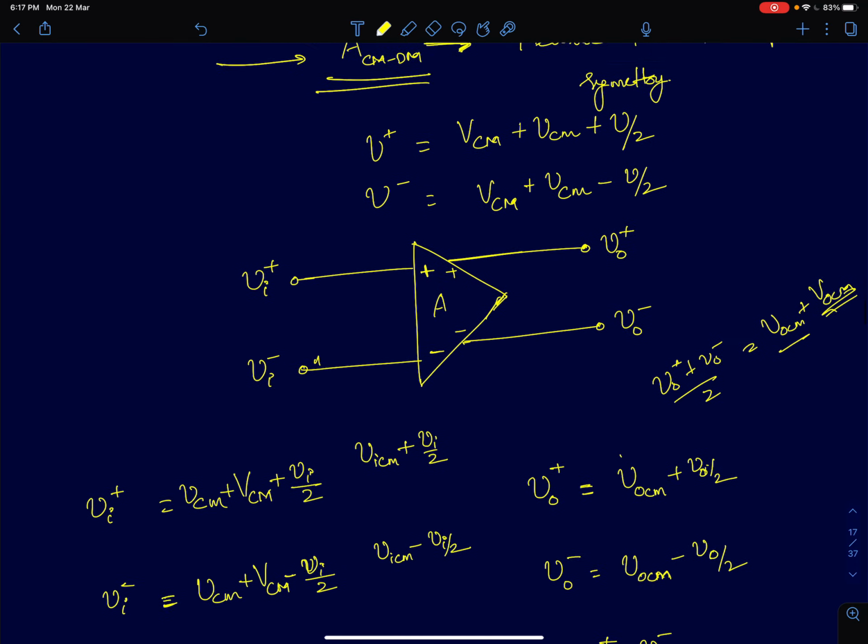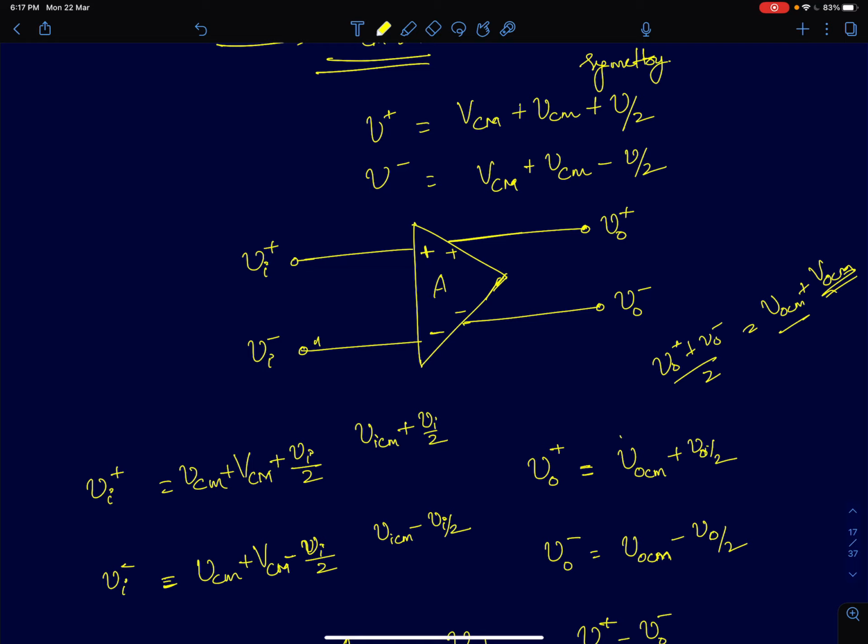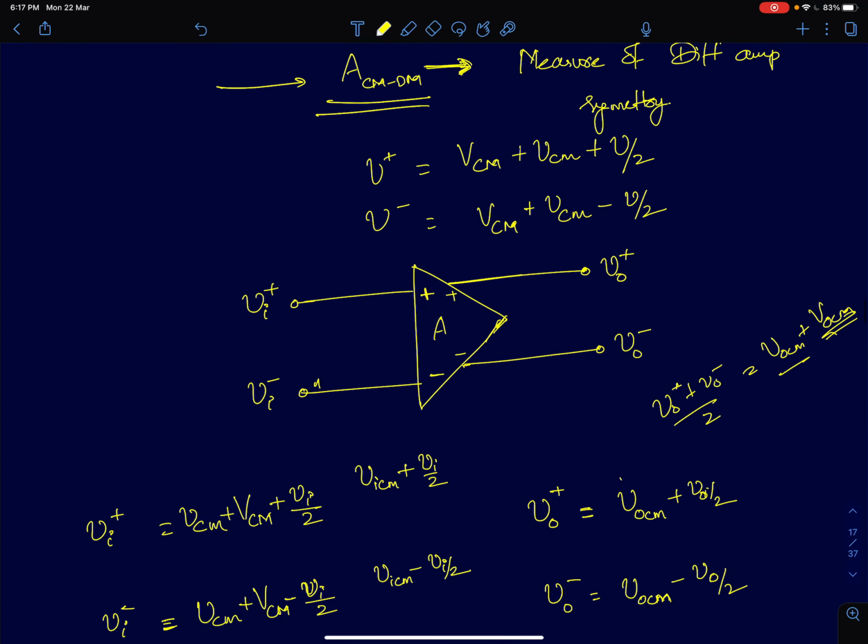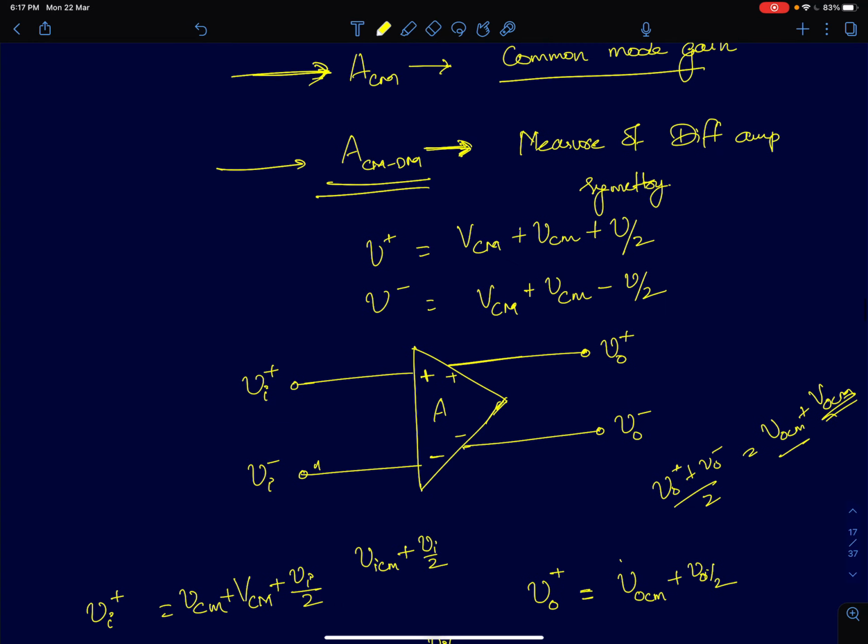So first I'll mathematically give the equations for these three parameters for a differential pair. In any differential system, we will always have two nodes which are going to have opposite variations with respect to some AC signal. I can generally write V plus and V minus as two differential signals.